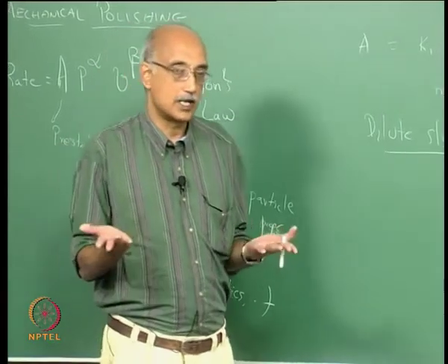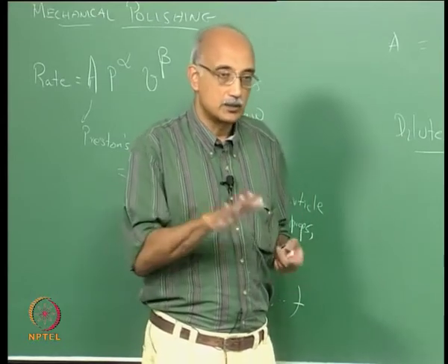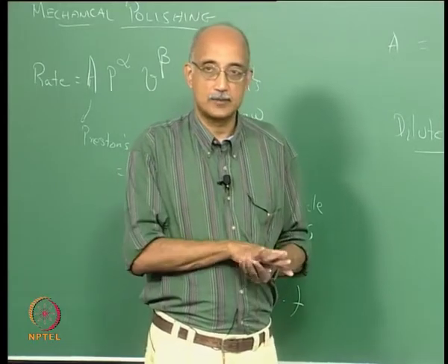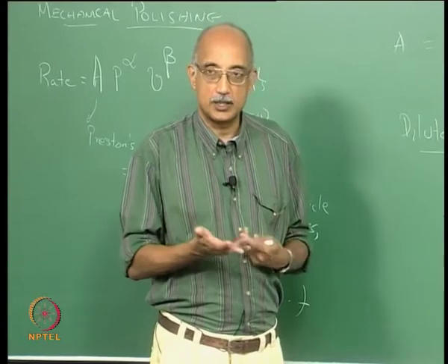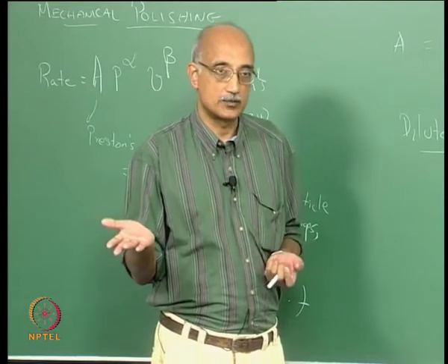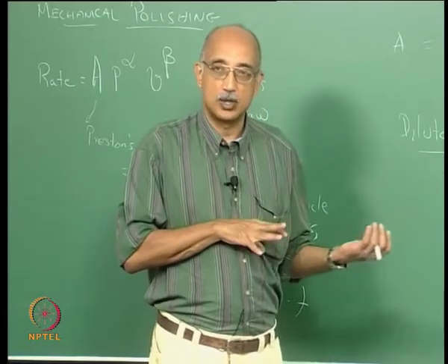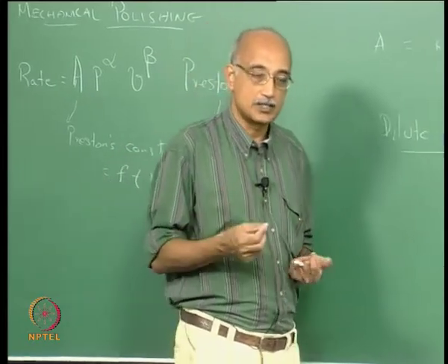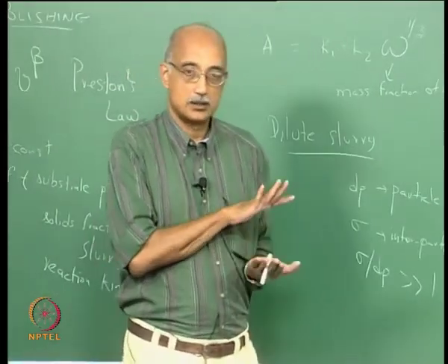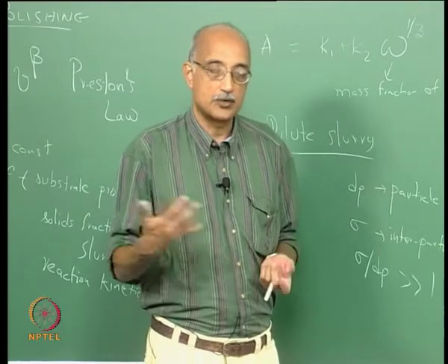So, now you have particles that are stuck on the surface which are foreign media that you really do not want on your product. For example, if you are using CMP on a silicon wafer, yes, you may be removing the surface roughness and also some chemical constituents, but at the same time you could be transferring alumina, which may be your polishing media, to the silicon wafer. This alumina then has to be removed before the wafer can be processed further. So, again the process of particle removal that we talked about in one of the earlier modules becomes important. You have to devise a mechanism by which these abrasive particles that are pressed into and lodged on the surface can be removed before the wafer gets sent for further processing.